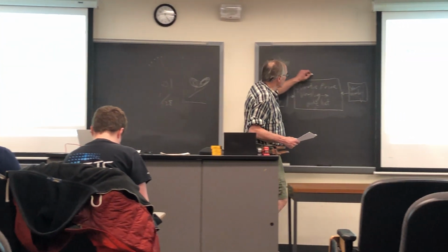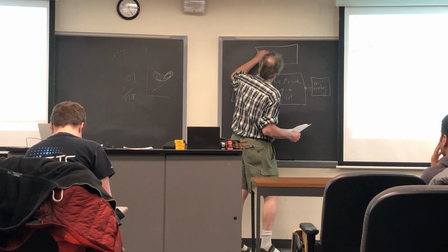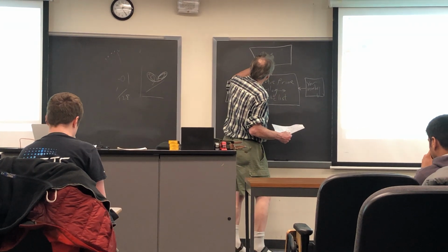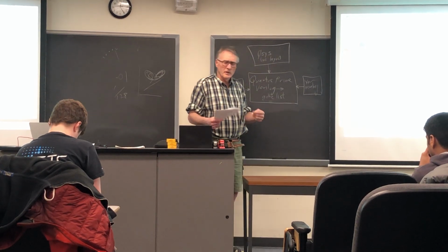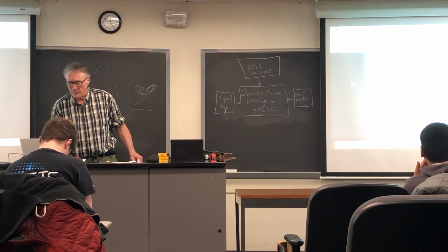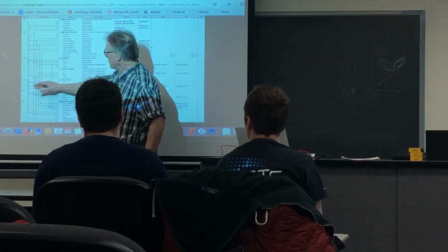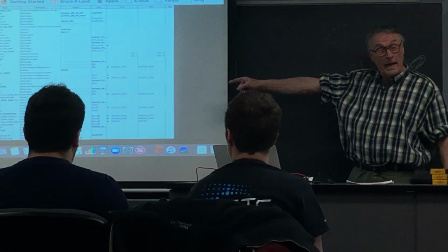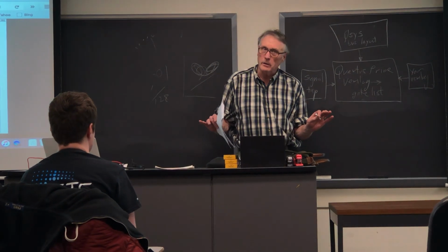There's another source here. There's going to be a Verilog module that comes in from Qsys, which is going to represent the bus layout that you designed. You're going to use a graphic tool, which I think I showed you last time, in which you have a whole bunch of modules and bus masters, and you think up bus slaves. This generates a gigantic Verilog file that's going to be fed into Quartus Prime. You don't have to look at it.